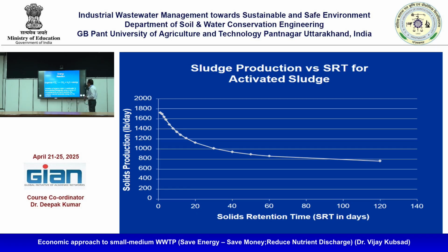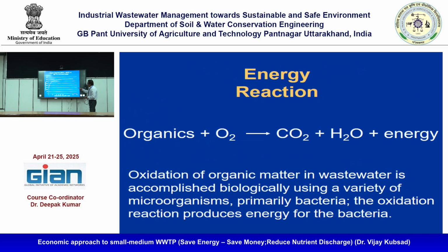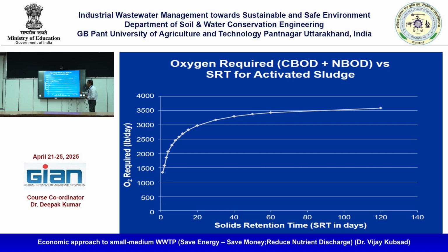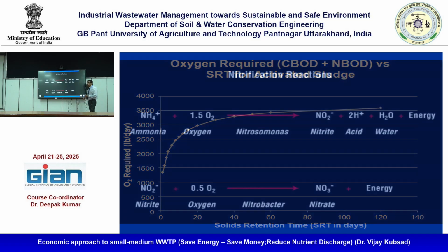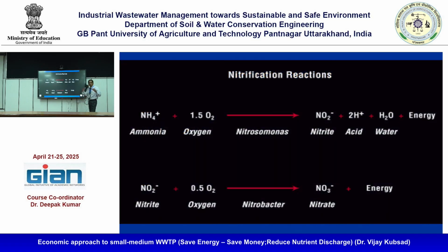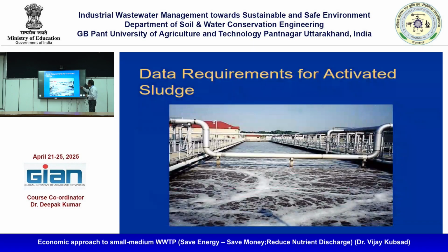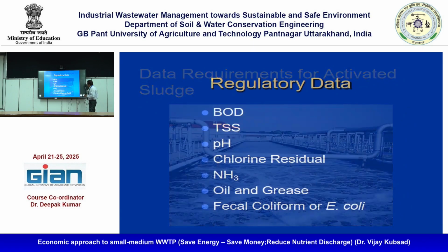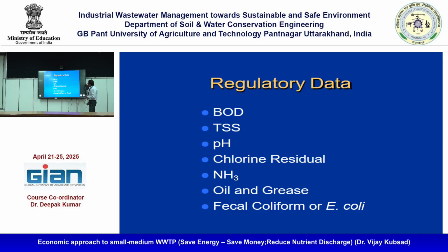So you have seen this reaction, the generic reaction, where the treatment is done. This is also the same in terms of the oxygen requirement, right? As the organic compound reduces, the aeration volume reduces. You have to think smartly. How will you find out whether this much aeration is required or not? You will see the loading and then you can decide. So you have seen this. This is the generic wastewater.